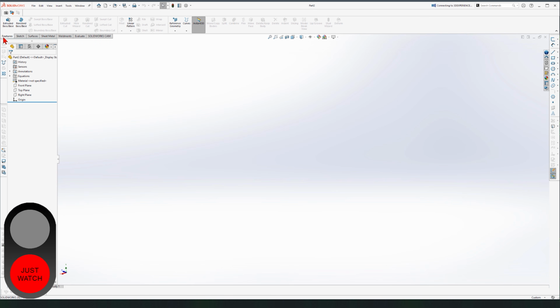Okay, quick review of what's gonna go down. This is our area of modeling, which is empty. And to you, it might look available, but you have to break it down before we can start actually modeling. The way it works is like this. Whatever 3D object we are going to model here requires a 2D sketch for the simplicity of our level right now. And every 2D sketch needs to be drawn on something. That something can either be a plane or a flat surface of an object. Given we don't have any object here yet, it must be on a plane.